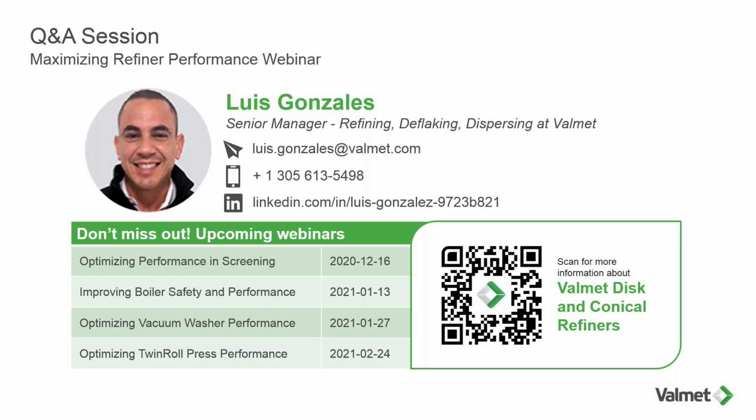Okay, great question. So we're looking at, for applications where the level of debris is high, somewhere in the 3 to 5 year range per side. So OCC applications for test liner, for instance, the level of debris, the amount of sand in there is fairly high, and the only lubrication that the splines have to float on top of each other is the actual process. So they're seeing that sand on a regular basis. So we're looking at about 3 to 5 years for that type of furnish and that type of application before you flip it around. So total is going to be 6 to 10 years for that type of application.